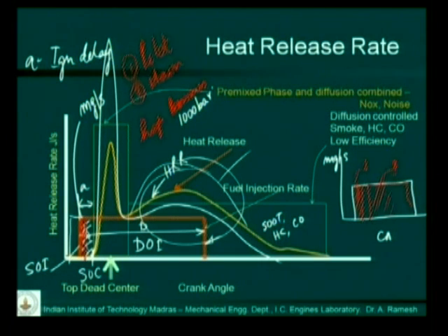3000 bar, one bar is 10 meters of water. So you can convert 3000 bar and see, it is 30 kilometers of water column. So such pressures, and in a normal, now common diesel engine, it is very common to have something like a pressure of 1500 bar.